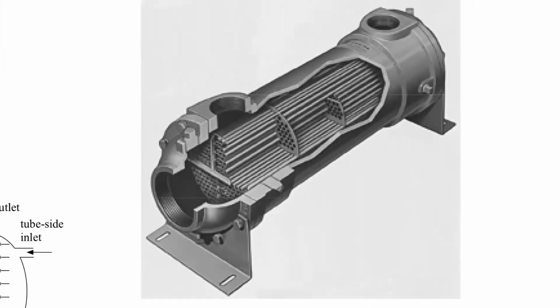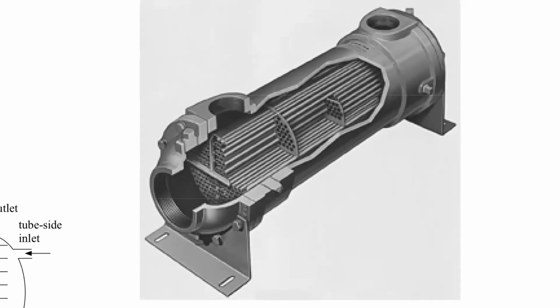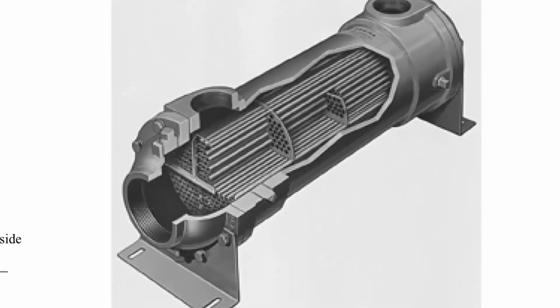Yeah, so here's a cutaway of an actual CFD of these. So you have these tubes that are going through these baffles and kind of complicated flow. So I won't ask you to model these directly, but you probably want to use a correlation on that.